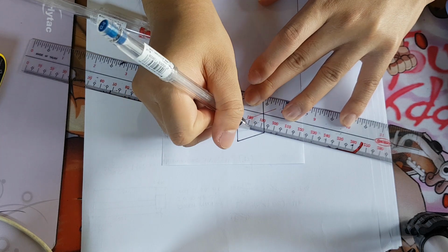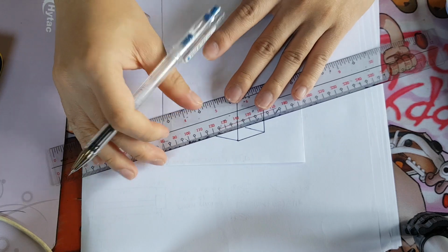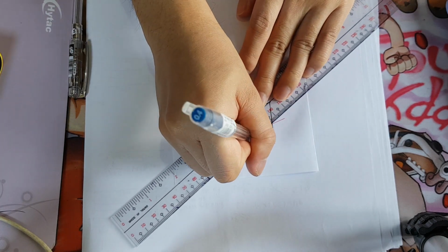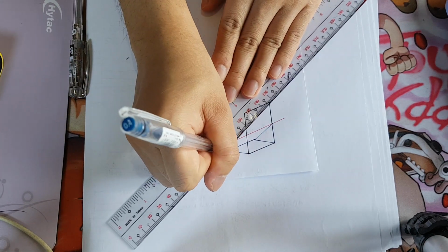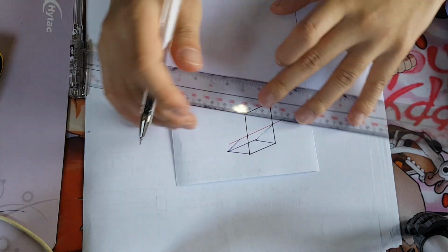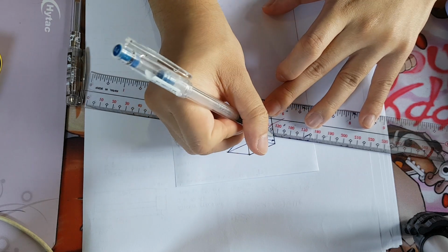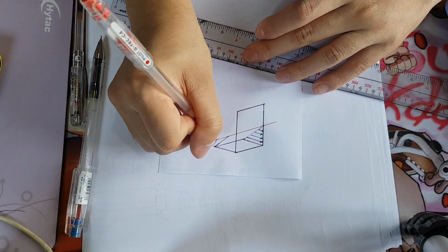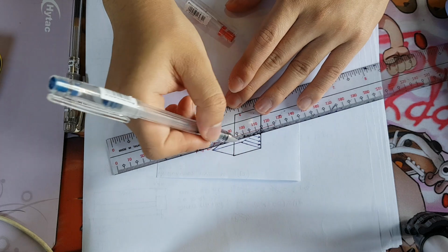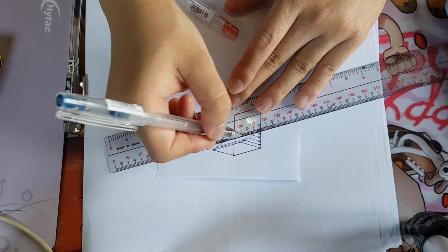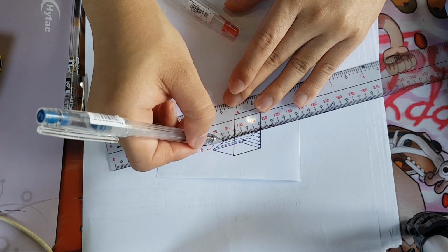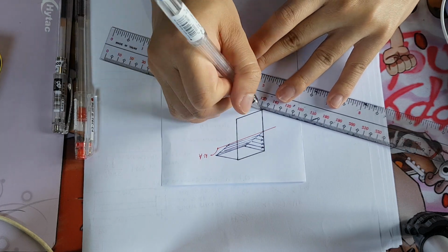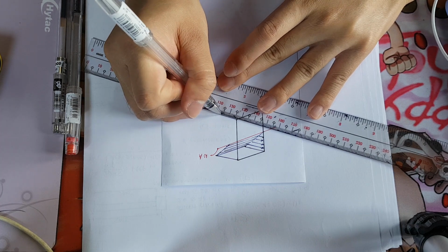So we have here the stress diagram. Okay, so we know that at the top it is a compressive stress. So we have here the compressive stress. Okay, since it is a compression, it is going towards the cross-sectional area. And take note that this is our neutral axis. Okay, so from the neutral axis down to the bottom, we know that it is tension. So more or less, this is how our stress diagram would look like.